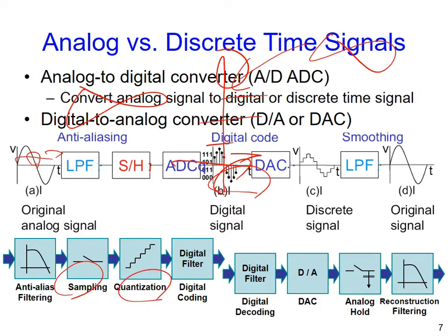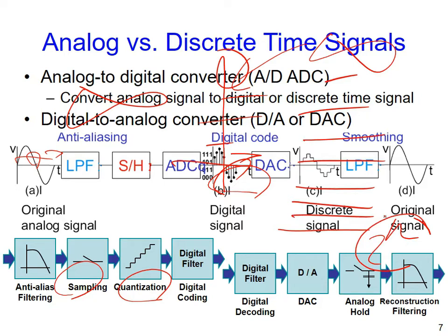All right, and what is quantization? We have a lot of quantization levels. If you have n bits, then we have a total of 2 to the nth power quantization levels. The definition of quantization in theory is to find the closest quantization level to your input sample. For example, here, this quantization level is closest to the current sample, then I use the number of the quantization level to represent the current sample.